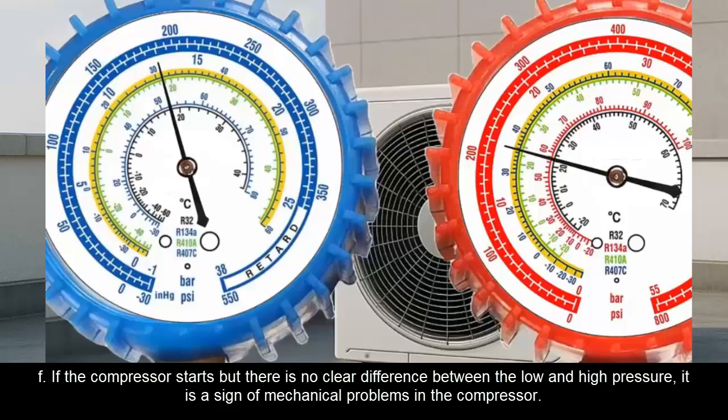F. If the compressor starts, but there is no clear difference between the low and high pressure, it is a sign of mechanical problems in the compressor.